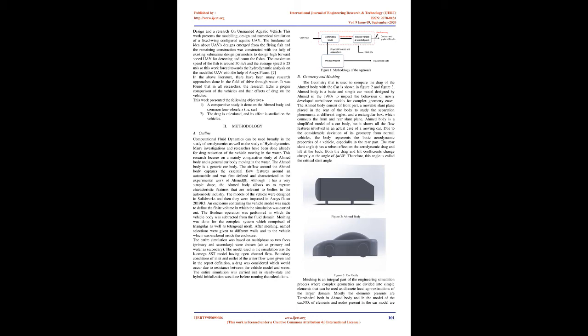Barsos considered phenomena of fluid slippage on hydrophobic surfaces, which can drastically reduce the skin friction drag. In this regard, the drag reduction of an underwater hull with an unseparated flow profile is investigated numerically. For validation purposes, the numerical results for the slip flow over a micron-sized spherical particle are compared with the available analytical results, where an acceptable agreement is observed. Phillips et al. presented a package of CFD simulations proposed to aid the designer in these areas.